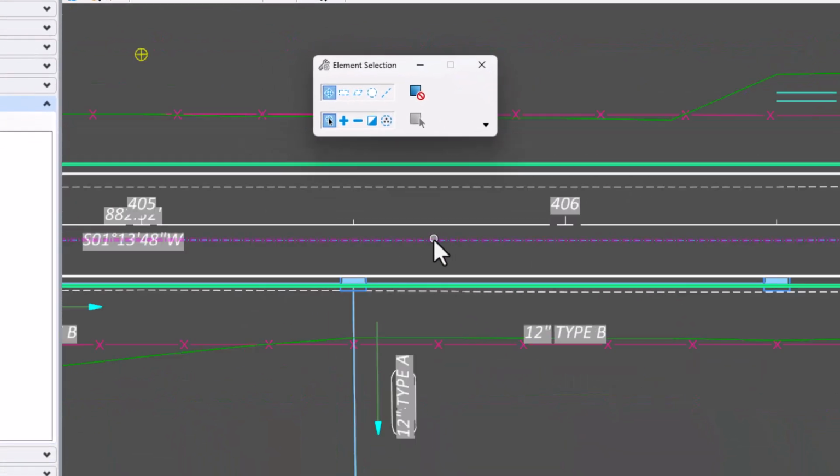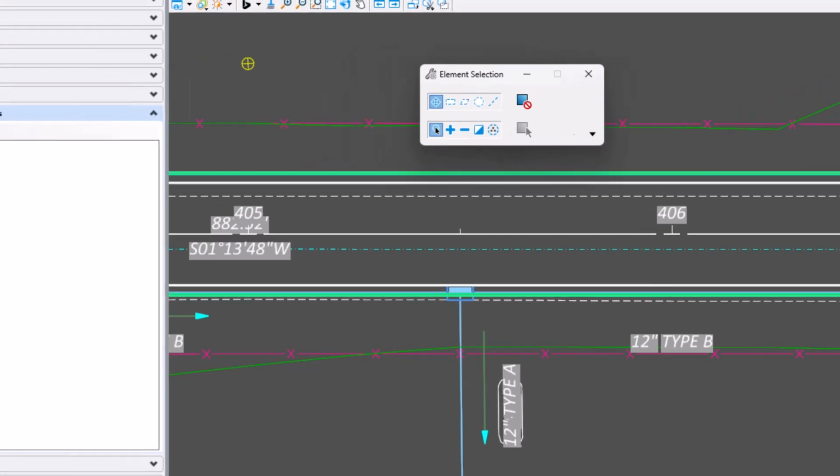I'm going to click this, and I'll reset to complete. Now one thing you'll notice is there's no flow arrow. There's no way to override the flow arrow. It's because it's in the 3D side of things, so you have to use element annotation and take the default and not override. But now that I did that, what I want to show is, I'm going to go back